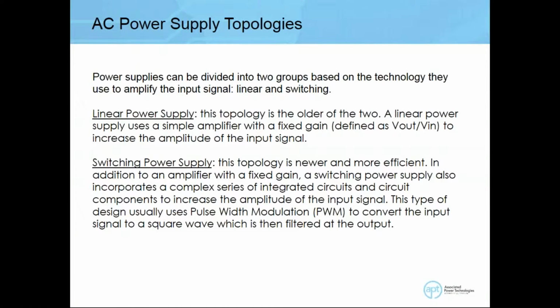Now these are bulky, in the sense that the transformer itself takes a lot of the weight. And it's really not that efficient, because a lot of the energy loss goes into just powering up the transformer. The newer technology is known as a switch mode power supply. For switch mode power supplies, you have integrated circuits working in conjunction with other circuitry. The main purpose of a switch mode power supply is that it generates less heat, is much lighter, and does all this on a smaller footprint.